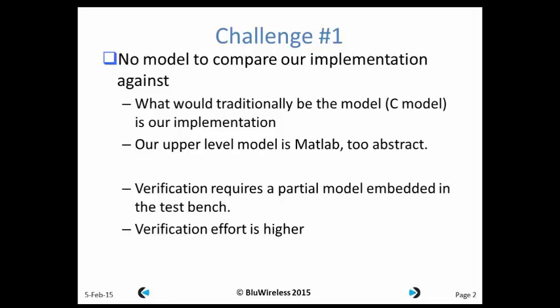For us, what would be the model, i.e. our C model, is actually our implementation. So we have it in SystemC, and we use C to silicon to turn that into the RTL. And the only other models that we have available to us are in Matlab, and they are too abstract and high level for us to use for what we do.